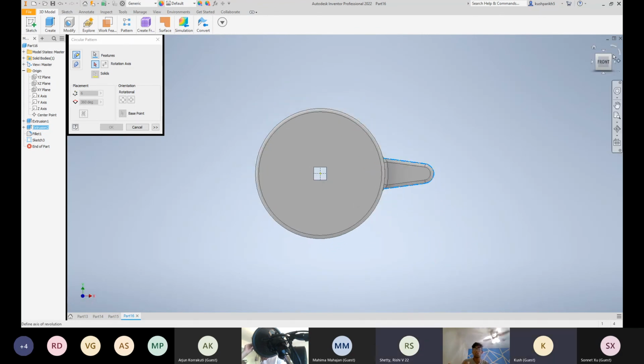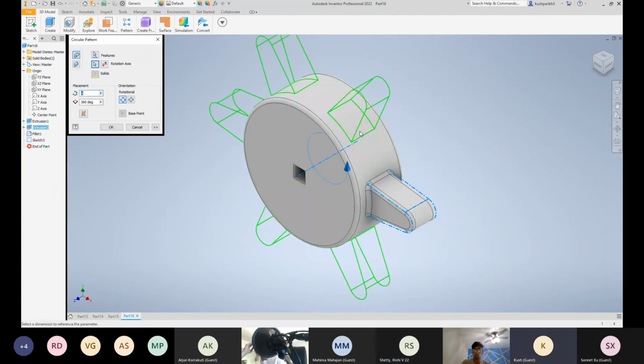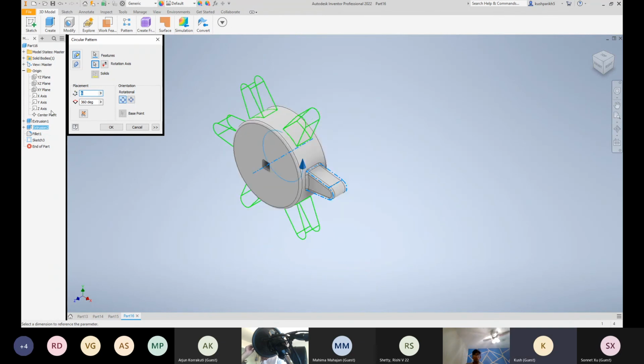Okay, never mind. That's usually not the center. Yeah, that's the edge. So then just click the circle. Yeah, that works. You see that highlighted axis over there? That dashed line. So if you select the circle, it will revolve around the center, so you don't have to guess. Alternatively, I suppose you could have also selected the z-axis, but both of them work.